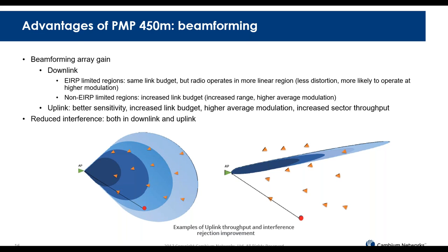But if we have multiple antennas at the access point, we also have a third term, which is the array gain. So the EIRP is going to be the sum of three terms: the transmit power, the antenna gain, and the array gain. Now, let's assume we have an access point which in sector mode has the sum of the transmit power and antenna gain. Here there is no array gain in sector mode, which already meets the EIRP limit of the region. If we switch from sector mode to beamforming mode, and now we also have the array gain on top of it, we cannot exceed the EIRP limit. If you already are at the limit, we cannot add the array gain on top of it.